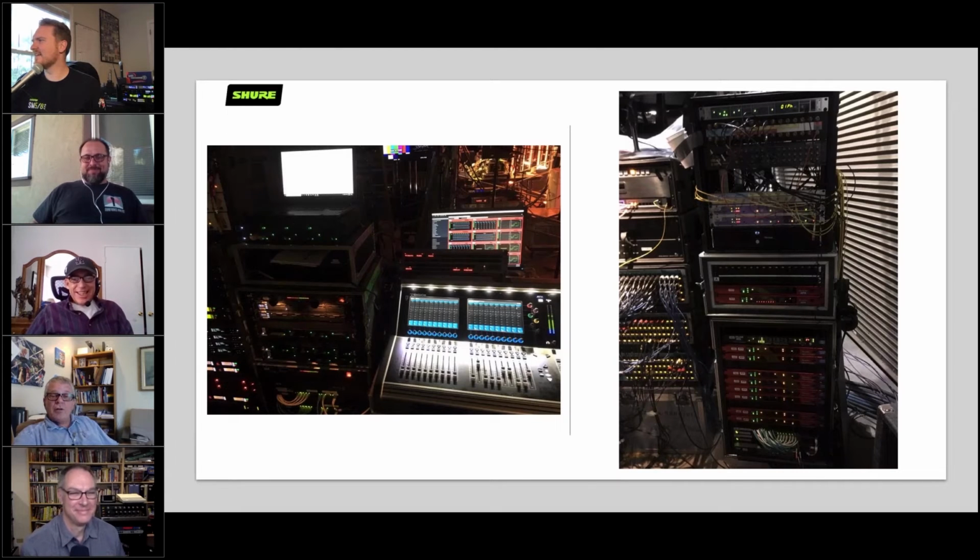The easiest way for us to monitor audio is by dropping in another small, independent console. It doesn't matter who the manufacturer was. The picture on the right is down in Splitland, about 150 feet away from Bill Kappelman in the RF racks. That rack on the right is my Dante rack and Dante to MADI converters. Just to the left of that are the interfaces to the production truck, the Hydras. Yeah, the Hydras.